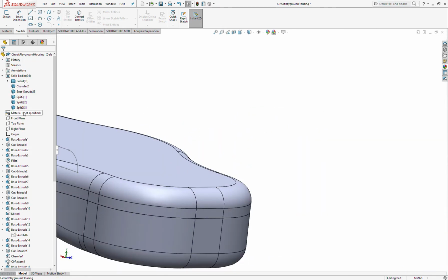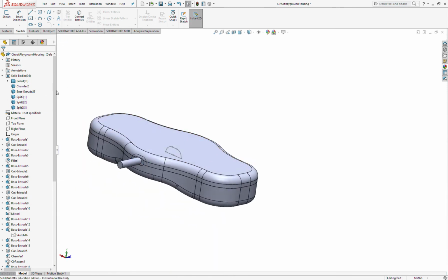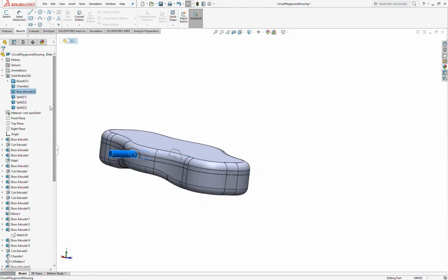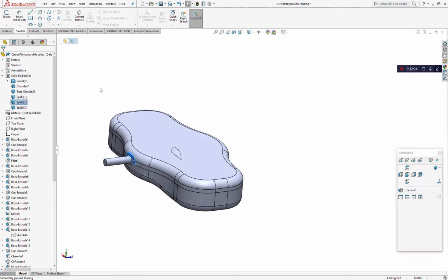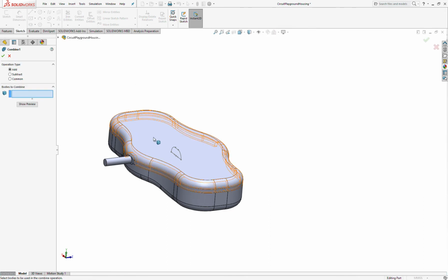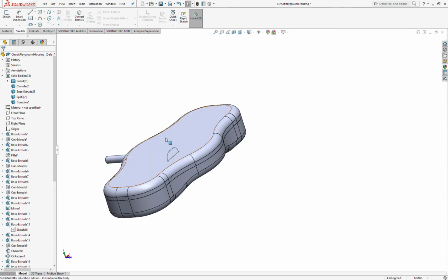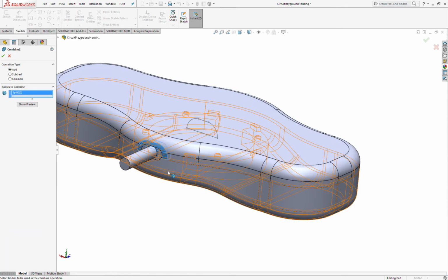And so now we may have actually plopped out the other side too. But so what we have is we've got the bottom, we've got the top, the cord, we've got the top, and then we have these two little extra doodads. What we're going to do is features combine. First, let's put these two back together with the add. So now those are back together. But now we're going to do the same thing, feature combine, but we're going to add this one to the bottom here.